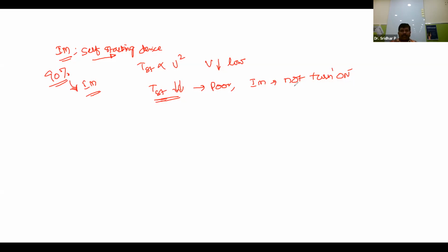So a lot of time you have to wait to pick up the speed. Sometimes it may reach the rated speed, or sometimes it may not. Suppose the starting torque is not sufficient to bring the induction motor to rated speed within a short period, and that motor is being used to make some ornaments, say to develop one glass, then it will not give a glass.